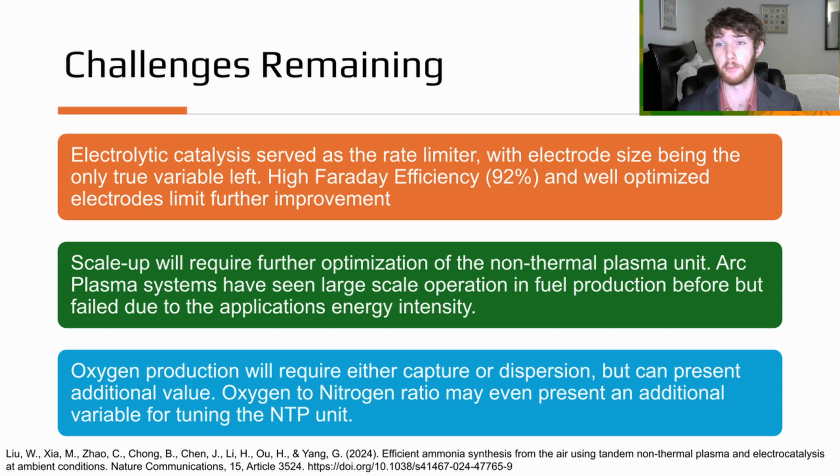They essentially had multiple production steps, where they're using a copper foam and then adsorbing copper oxide. Relatively complex, but because this is a cathode reaction, there's going to be some significant fouling and scaling concerns there. I don't think that's really well addressed in the paper, which makes sense because they're likely working with relatively pure compounds and not seeing any significant contamination. That's going to need to be addressed before any kind of pilot scale research can be done.